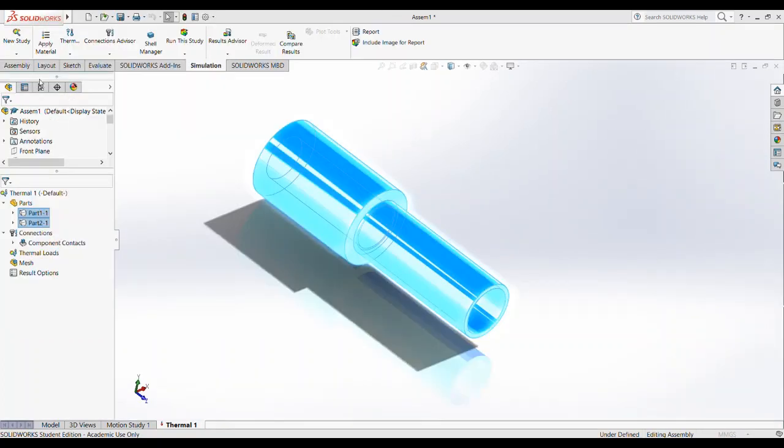I'm going to go to aluminum alloys. So there's a SolidWorks materials and there's the DIN materials, and I think it's kind of the same. But just go ahead and go SolidWorks materials, click that, go to aluminum alloys, and it doesn't really matter. From a thermal standpoint, they all pretty much have the same thermal conductivity. These alloys and tempers are more from a strength standpoint, but usually if you want to get used to a very common alloy, it's 6061 T6.